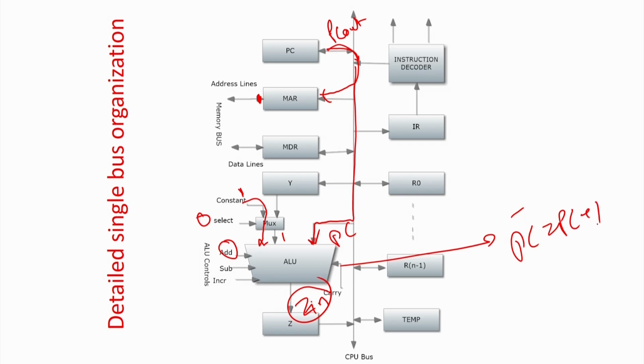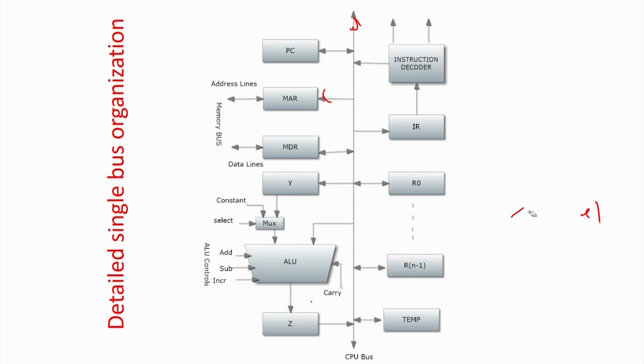So, you are executing three basic things. You are incrementing the value of program counter by the ALU, loading the value in Z, and also loading the value of program counter to the memory address register so that the instruction can be fetched. At the same time, memory also has been made to be in read mode. So, these are the signals which correspond to the first stage. Let us again clean it up, because we will have to revisit this figure many times.